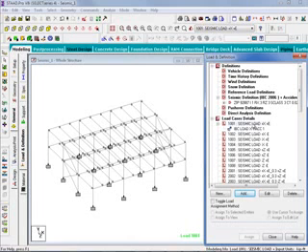And here I can see that my first seismic load case is complete. I would then proceed down the list of my 1000 series loads until all of my seismic load cases were populated. Let's demonstrate this process for seismic loads in our X direction.